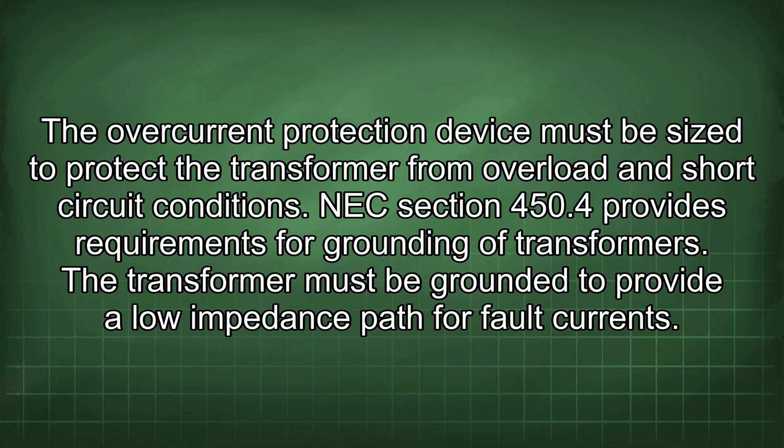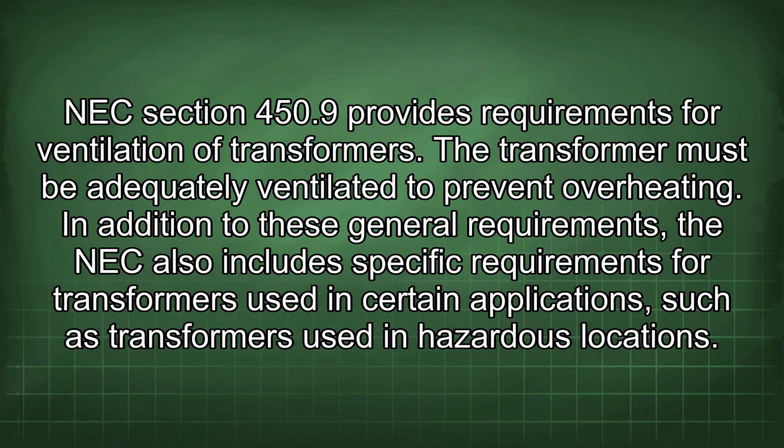NEC Section 450.4 provides requirements for grounding of transformers. The transformer must be grounded to provide a low impedance path for fault currents. NEC Section 450.9 provides requirements for ventilation of transformers. The transformer must be adequately ventilated to prevent overheating.